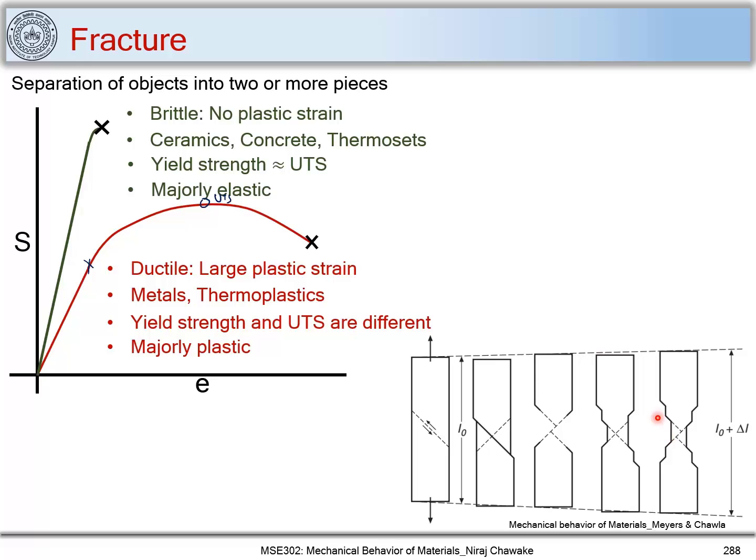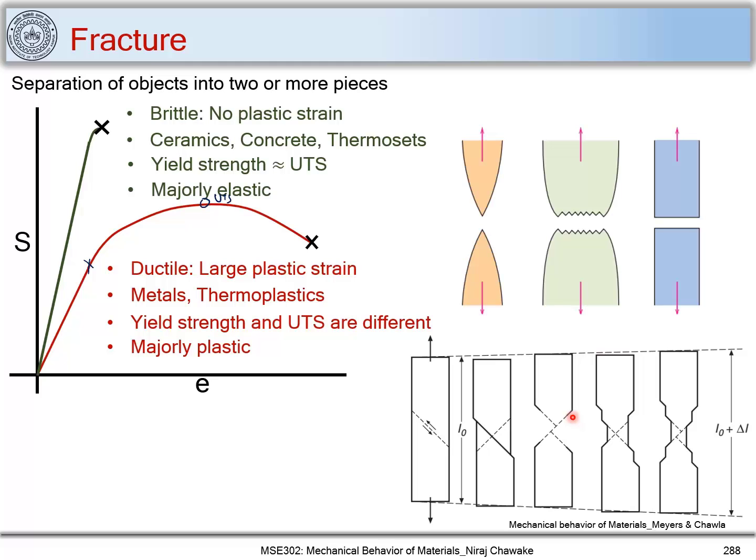Now, based on this fracture surface, which we obtained during a uniaxial tensile test, we can say what the nature of the fracture or the nature of the material can be. So let's look at some of the geometries of fractured samples. Here in this case, the area is much narrower, as much as equal to a point. Such a fracture is demonstrated by ductile materials.